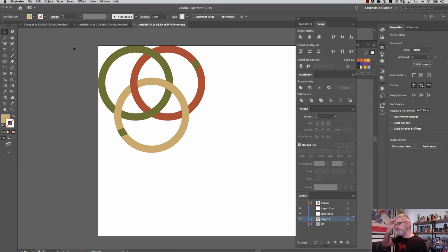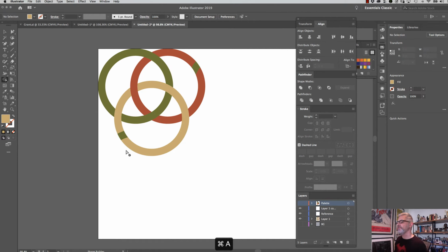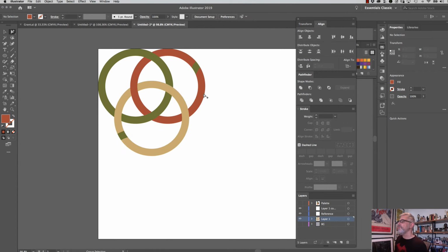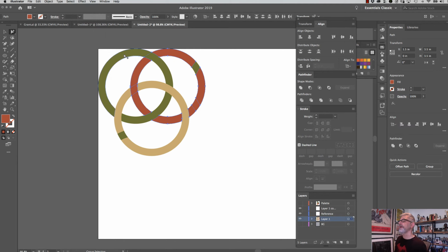Now, let's take a look at that pattern again. We're going to do the same thing, but this time they should interlock the way we want them to. So I'm going to select the whole project again. Now I'm going to go to my Shape Builder tool, and I'm going to select all. The other way to do that would be just to simply select the color that you want, and then say Select, Same Fill Color. Okay, and then Unite. So that unites that into a single shape. Okay, so now our shape is clean.